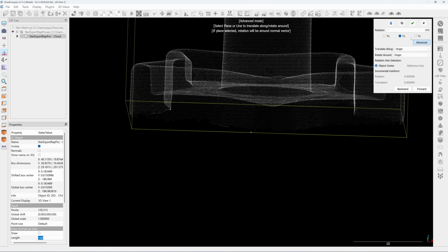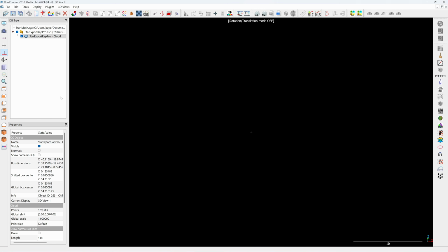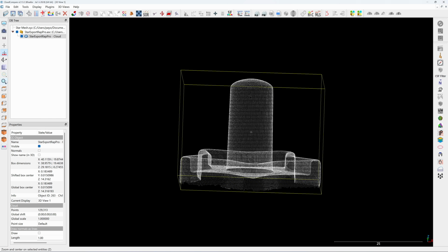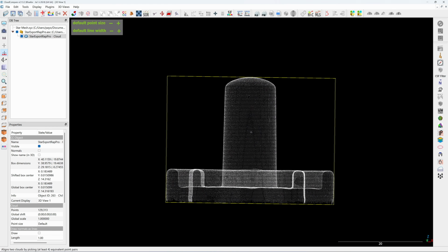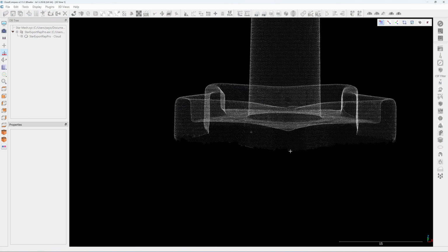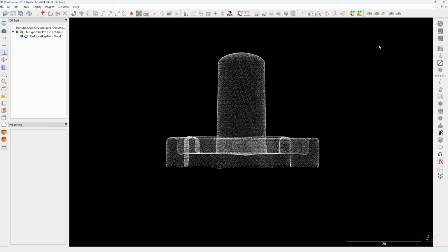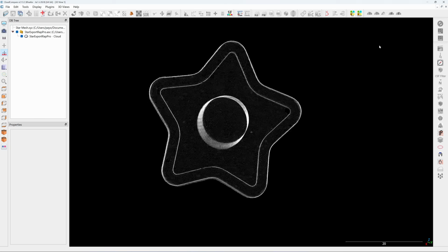So I do the same thing. I move this up in the Z direction by 201.3, forward. Click the check mark. Now it's moved up. I'm going to click here. See this point? Let me click on the coordinate checking. This point will be 0.02 millimeter from the origin point. Now this point cloud is ready for reverse engineering with FreeCAD.